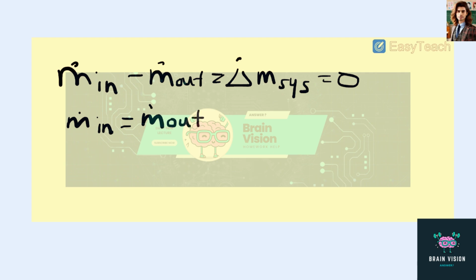Now, if we go ahead and write out what m dot is, this basically means that rho1 A1 V1 is equal to rho2 A2 V2. For rho, we can use the ideal gas law and plug in the geometry for the areas.